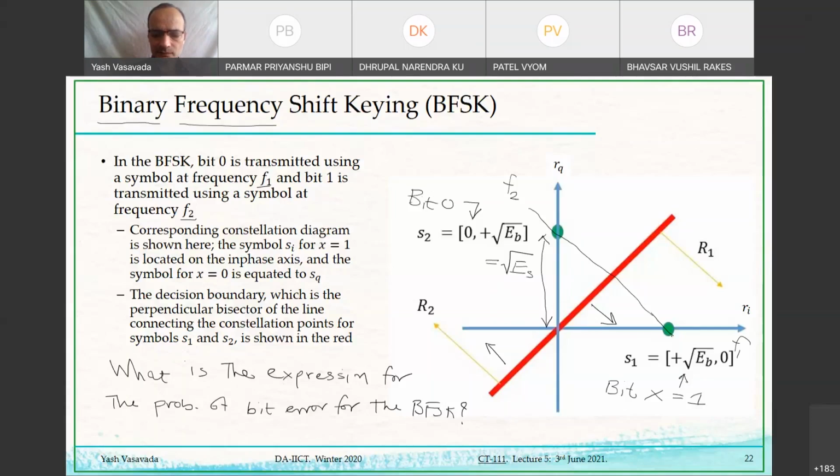So in similar manner, we can derive as we derived for BPSK error. Yeah. But what is the answer? We don't need to go through the whole derivation, remember? From the last time, do you remember what we concluded about the theoretical expression for the probability of bit errors, especially for the constellations which have only 2 points? Q of A by sigma n. But what is A here?